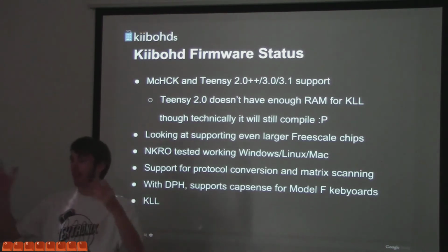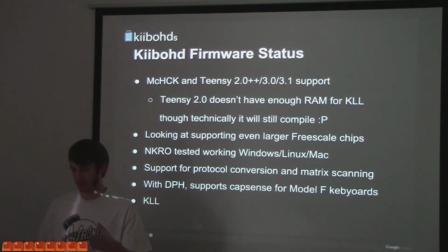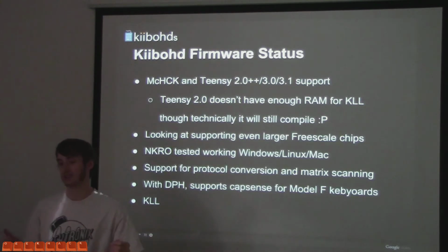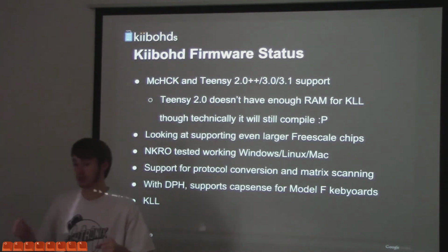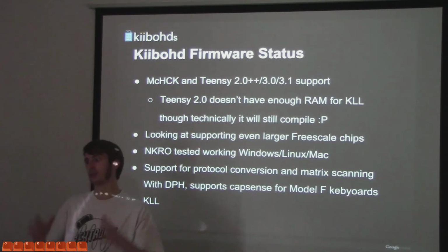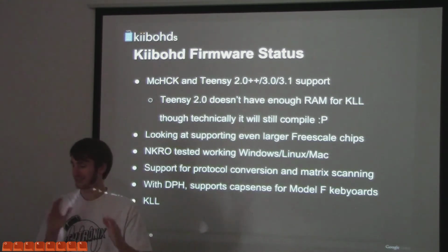On top of that, microcontrollers have gotten faster and faster. In the keyboard we're shipping, the Infinity Keyboard, there's a 48 megahertz ARM core. I can do a lot of things with 48 megahertz. A lot of computers not too long ago were faster than that. So with all this extra RAM and extra space, I can start to offload what the USB spec says is the host OS problem, which is the layout. USB does not define a layout. According to USB, every keyboard is US ANSI, a normal US keyboard.